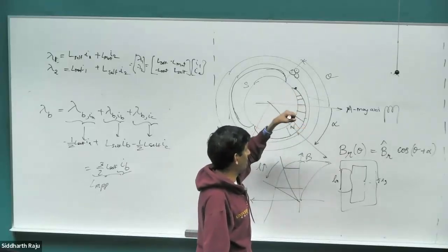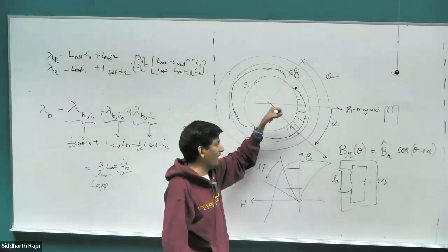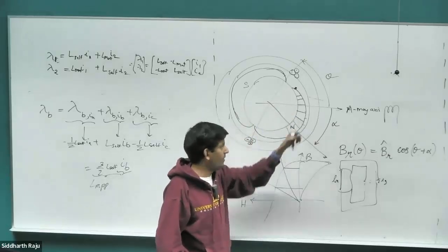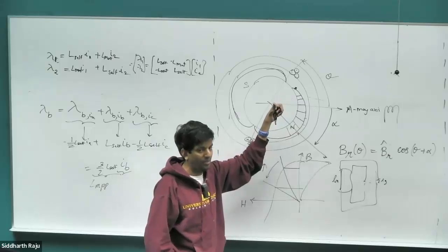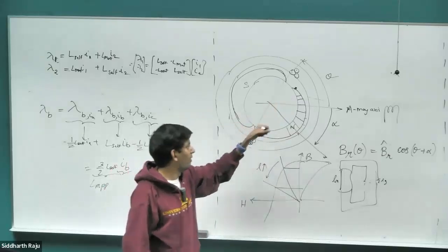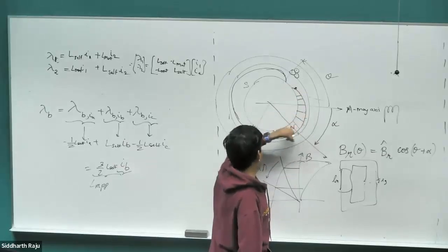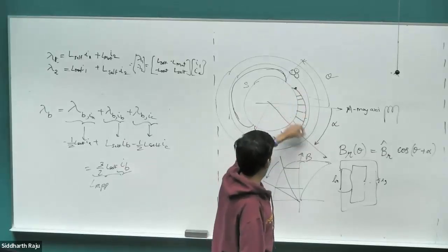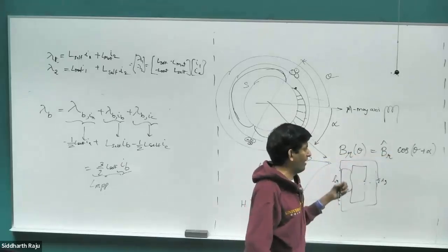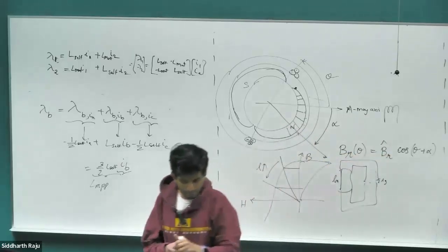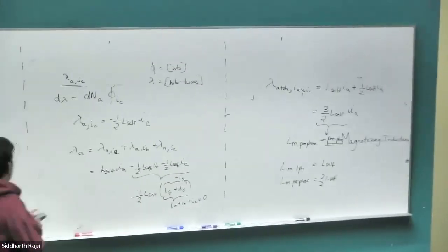When you form the material itself, once you create the magnet, you don't want to chip away elements of the magnet to create that larger air gap, because magnets are quite brittle, they'll break. So when you create the material itself, you'll create it with a shape with larger air gap length. It's called shaping the magnet, and you can create any kind of B field in the air gap that you want just by shaping it. Right? So once we have the B field in the air gap,